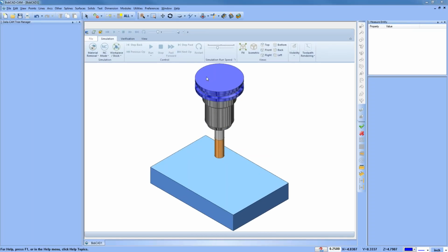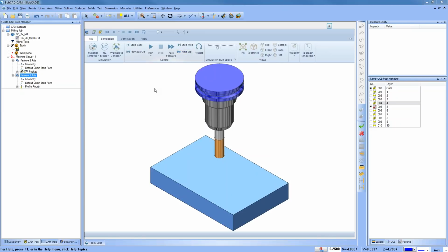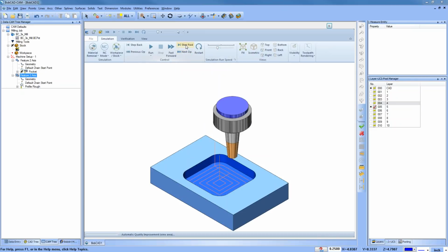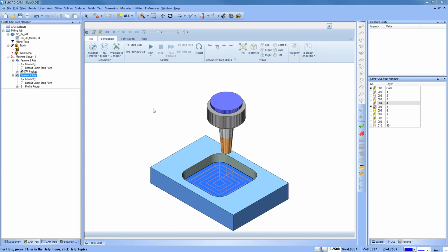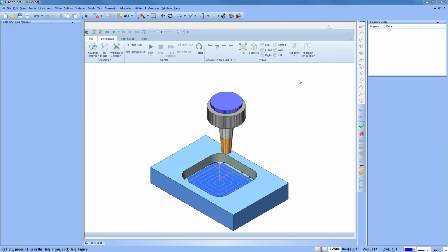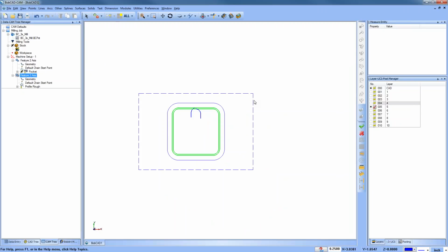This way you can walk the tool into that profile versus just taking a very aggressive cut. We'll go next on our pocket here, and then step through, and you can see with this tapered end mill, we're able to come in here and put the draft on the wall. Because we're taking 2 passes, we're not going to overload the tool. That would depend on how much draft was on the wall, but using your different tool types, you can attack these different scenarios. That's an example of doing a tapered-wall pocket where you're taking multiple passes.